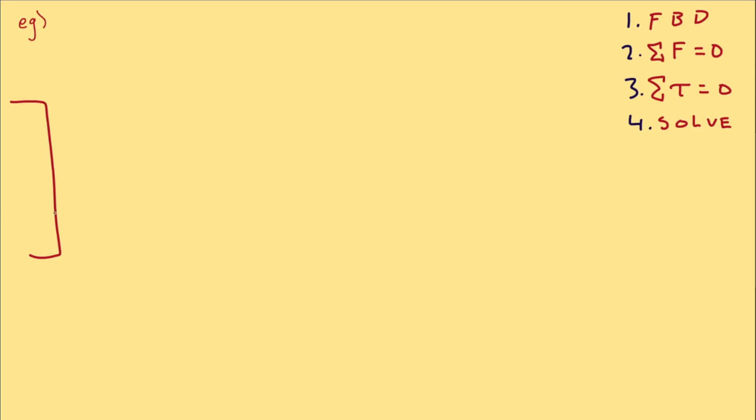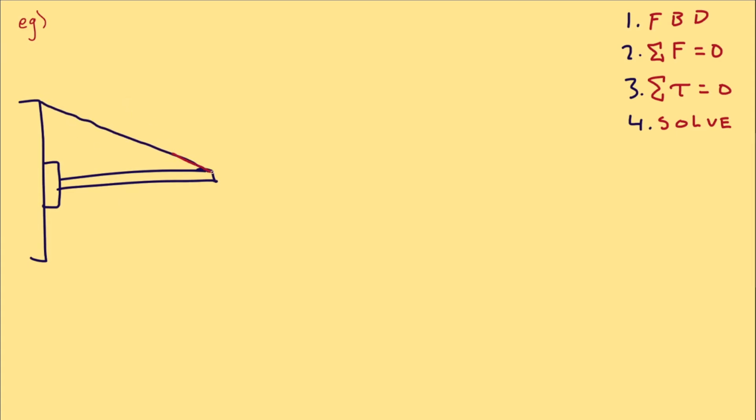It's going to look pretty similar to our sketch. We've got the wall, we've got the hinge, we've got our arm coming out, and there's the cable. This cable, we've got the force of tension. The arm right in the center has its weight. It's in the center because it's evenly distributed in terms of mass. And this weight is equal to 800 newtons. And we have the force that the hinge exerts. And each of these forces have an X and Y component happening.